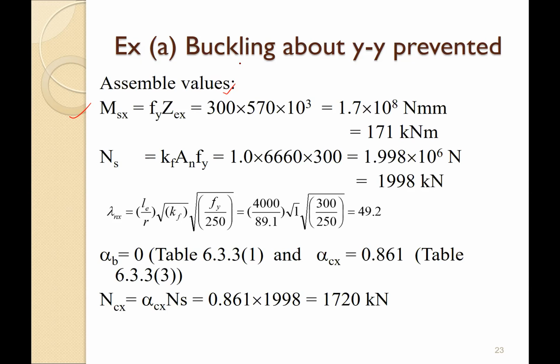And remember, when you are considering bending, we always use the flange properties. We talked about this before. The flange yield stress Fy will be used for the bending section capacity. And for shear, you use the web capacity, because the logic is simple: the major bending load will be carried by the flanges. So Fy times Zdx, this is Fy and this is your Zdx.